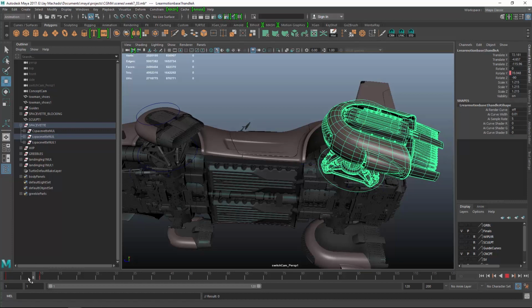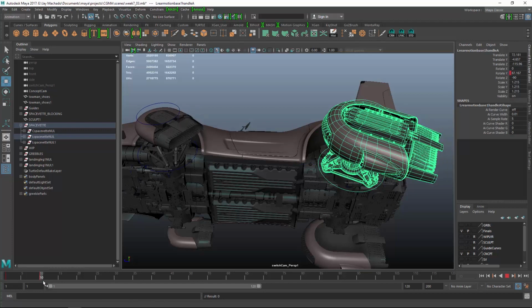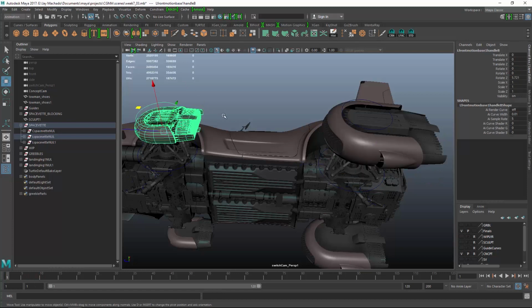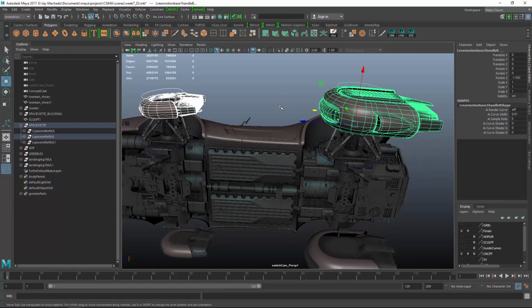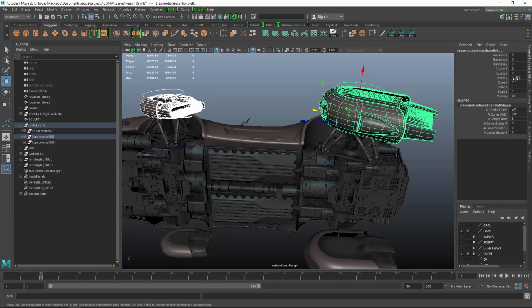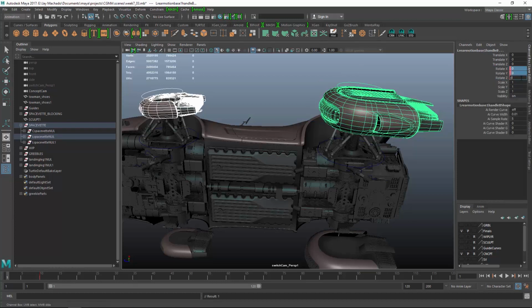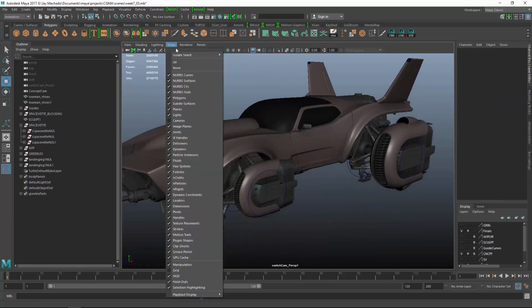Basically what happened in this case was I had rotated it by 90 degrees in X and 90 degrees in Y, but what I really should have done is rotated it negative 90 degrees in Z, and I would have gotten the correct order of rotation, I guess, to get this to behave the way I wanted.